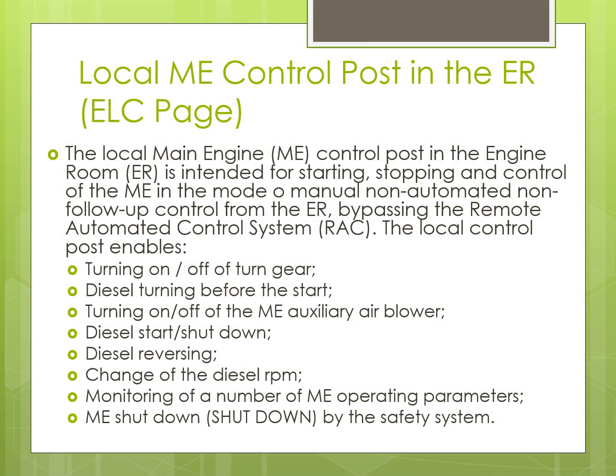Local ME control post in the ER. The local main engine control post in the engine room is intended for starting, stopping and control of the ME in the manual non-automated, non-follow-up control mode from the ER, bypassing the remote automated control system.